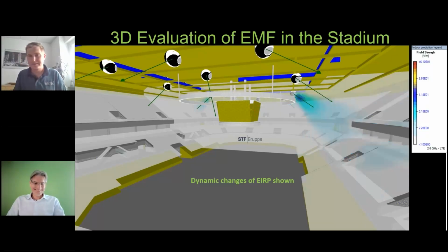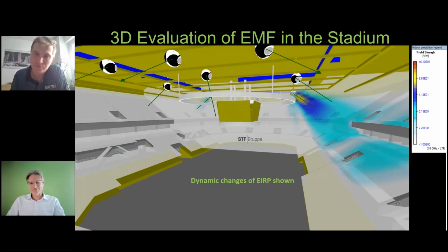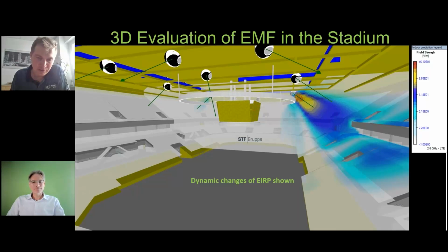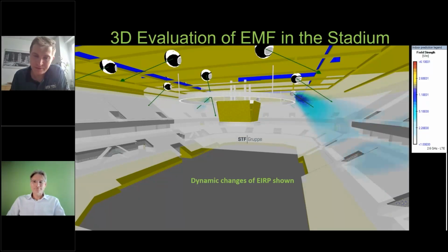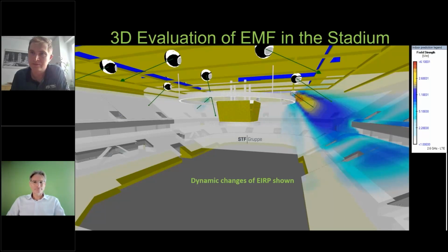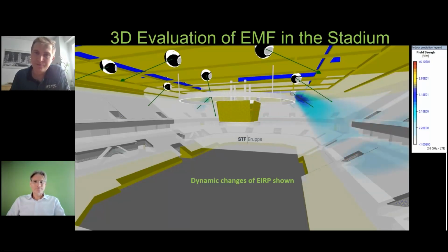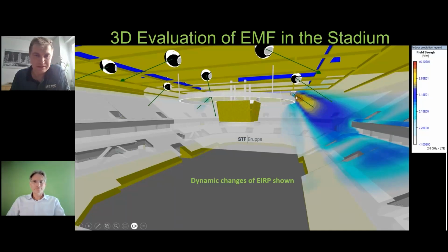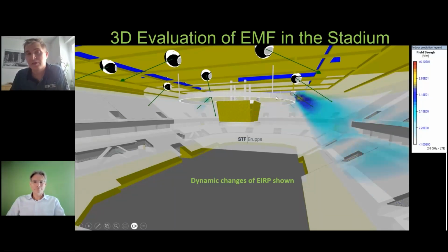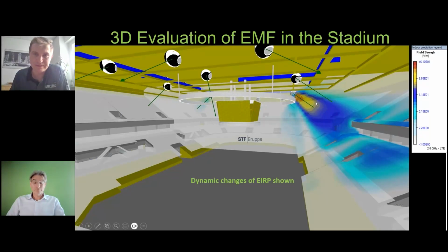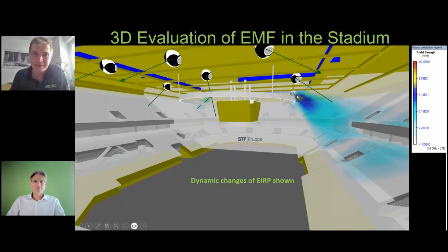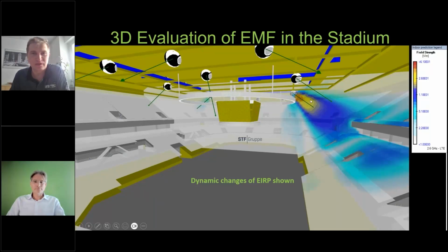Just have a look. This example is to visualize for you the EMF calculation. The regulation limit, which is also valid in Germany, is 61 volts per meter. But just to visualize this maximum, I have to set a really ridiculous power level like 600 watts, which is typically not achievable. This is just to showcase that it's possible to visualize the body area where you would not be allowed to be. Typically, better not to go there.